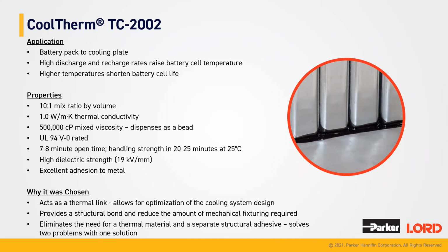It has an open time of 7 to 8 minutes and will reach a handling strength in 20 to 25 minutes when cured at room temperature. It also offers excellent adhesion to metal and provides a high dielectric strength.